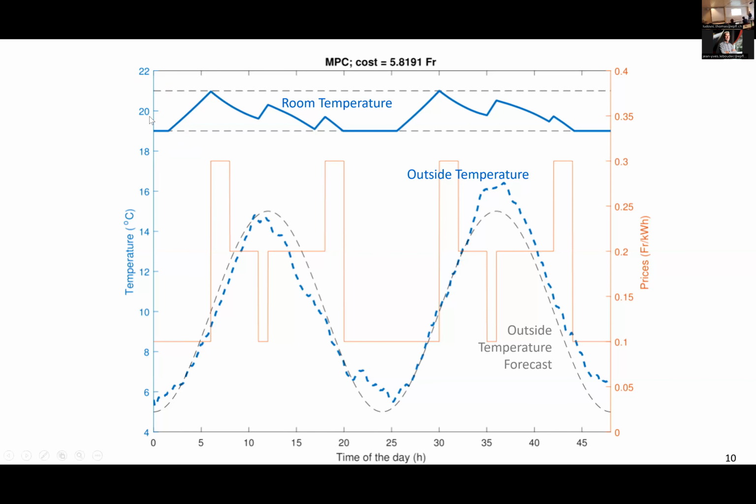If we don't have a dead band, there is not much you can do. If you want the temperature to be exactly 19 degrees, then as soon as it deviates a bit, you need to heat, and you stop heating as soon as you sense a measurable difference between 19 and what you measure. That's what a thermostat is doing. The thermostat, in practice, still has a dead band, but a minuscule dead band, it keeps the temperature almost constant, equal to 19 degrees, for example. Here, I'm allowing some variability. This is modeled by our penalty function.